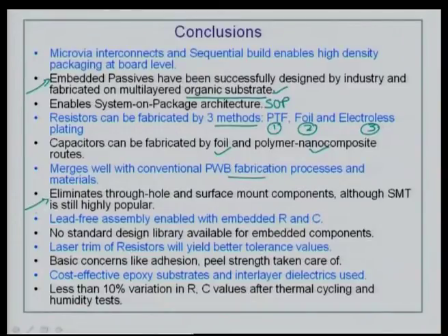Although SMT is still highly popular, that technology is going to exist definitely for the next 5 years based on the kind of equipments that we are seeing, and it is highly popular. We are not going to see a radical change, although embedded passives are slowly getting into the thoughts of many industry people. Lead free is possible with embedded R and C. No standard design library is available. Laser trim of resistors is possible.